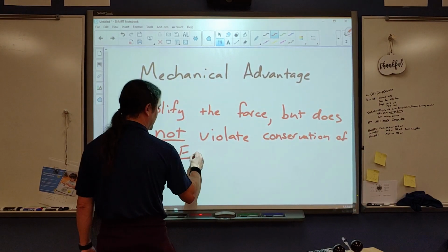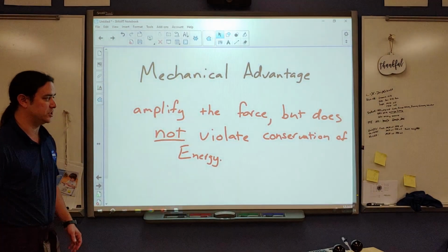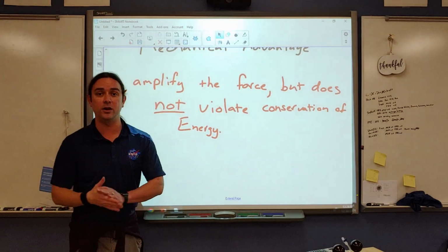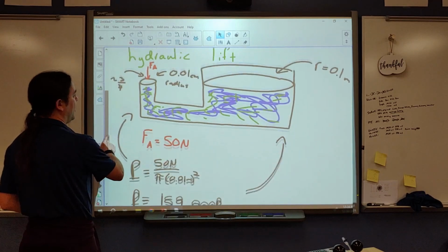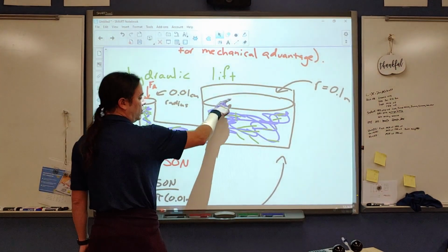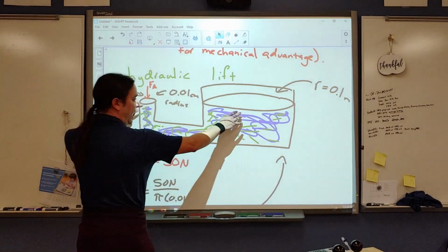This is a common mistake that students make. They think, hey, we're getting this much bigger force and therefore the job is easier. Well, it's still going to require the same amount of energy. The same thing that I'll bring up here is, if we go back to our hydraulics, if I push this down by 1 centimeter, will this go up by 1 centimeter? Well, no, because I'm only pushing a small amount of fluid out of the way.